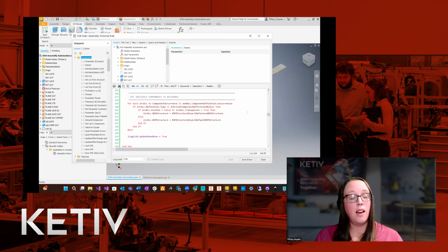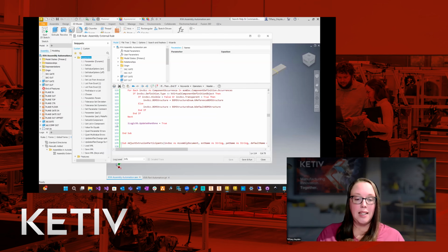That can be edited. It's just thinking about using assemblies for bigger than what you are doing right now, when you are dealing with a lot of template assemblies, where you have maybe half the components in your assembly that you want to reuse, but we don't want to count them in the BOM. It's good practice to just loop through them and make sure that they're visible. If they're not visible, then we don't need them. And then the last thing we do is an update when done.